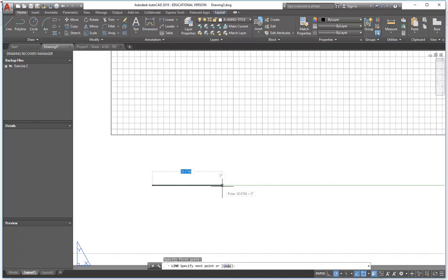and on the page, in paper space, try to think about the sizes. So maybe I'll start by drawing the full length of my scale bar. So I'm going to do a short one, which would be 5 metres. A long one would be 10 metres. So 5 metres, which is 5,000 at 1 to 50. Probably should have done 1 to 100 because the math's easier. But 5 metres, okay, so 5,000 at 1 to 50.